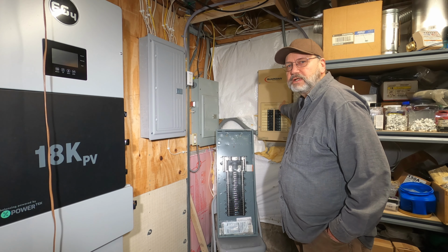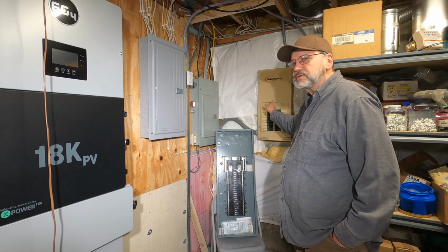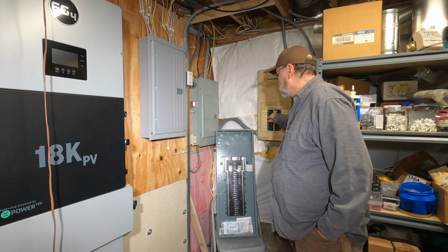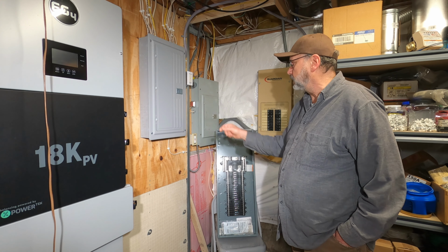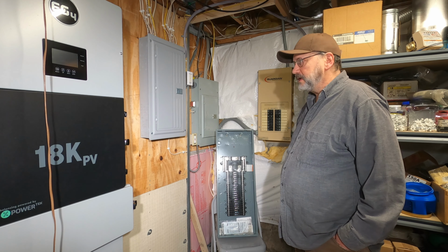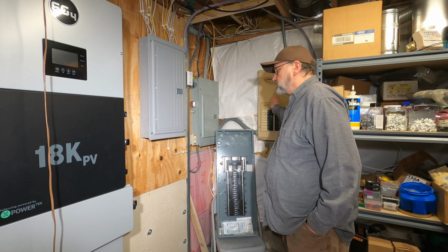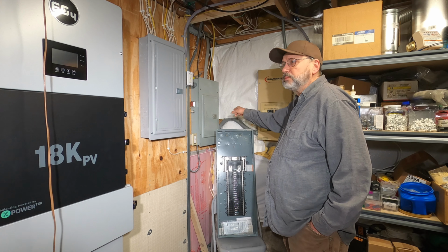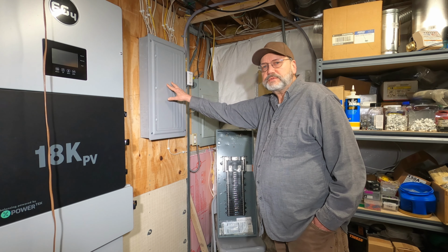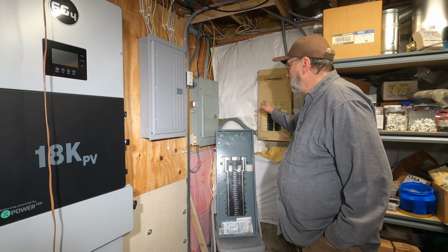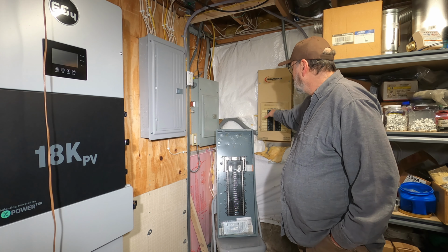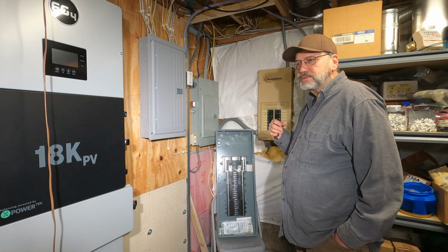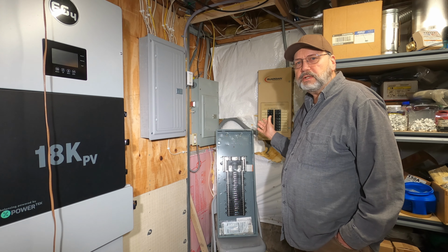This is the Guardian Generac transfer switch panel, which is actually a 100 amp sub panel itself. So I have a 100 amp breaker from here feeding into here. But the interesting thing is that this panel is fed from the main panel from a 70 amp breaker. So ultimately this only has 70 amps available to it. All the loads that are in here were always in here, and this was always just fed by 70 amps. So I know that it's not going to be a problem at all. It never has been.